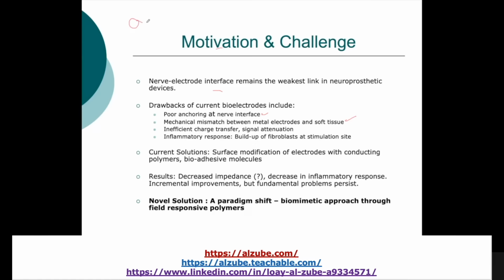So you have the stem and into the bone. Let's say here we have bone. You can see that you have a metallic part, the stem, and then you have the bone around it, and they have different mechanical properties. Because of the metal being strong, we have something called stress shielding, which means that the bone around the metal will not be sensing loads as usual because the metal is holding the largest amount of load.